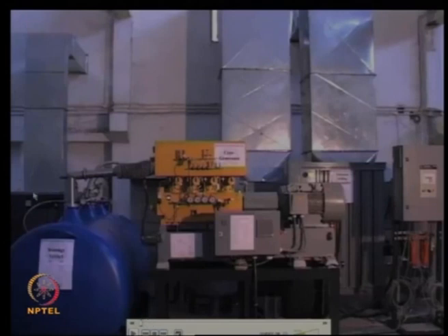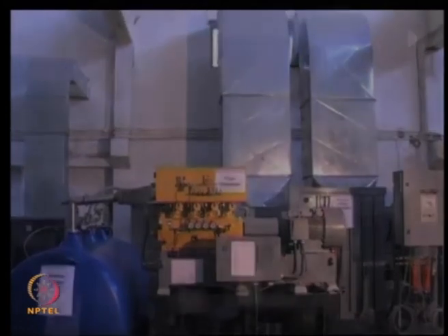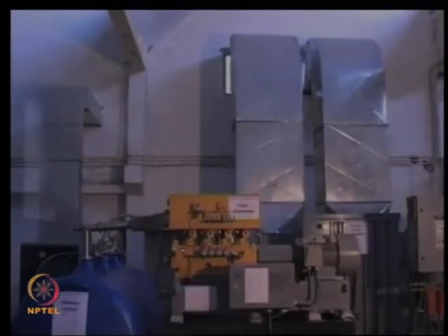The air gets compressed over here, then the air goes into the PSA plant here, which is pressure swing adsorption. The nitrogen is allowed to flow ahead, while oxygen is not allowed to go. Here the nitrogen gas comes and enters the cryogenerator. It gets condensed, and the condensed nitrogen, or liquid nitrogen, will be stored in this dewar. This is, in general, the plant structure. Now, let us see each component from close distance.